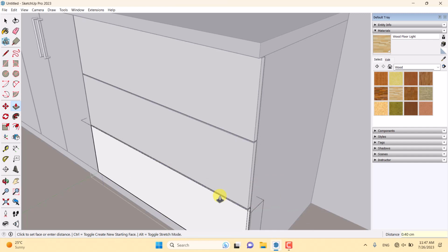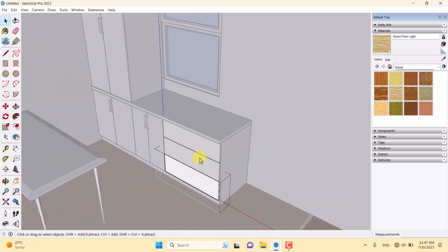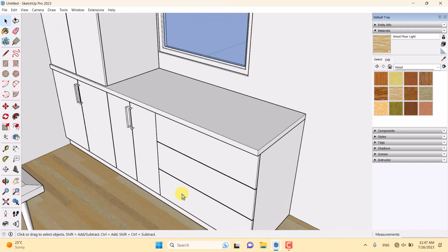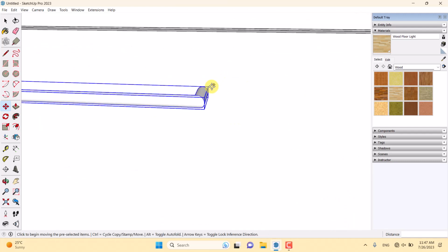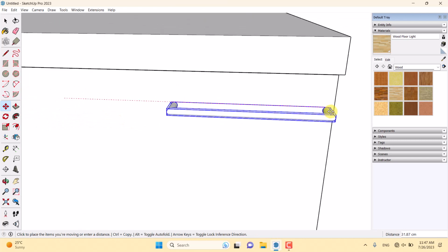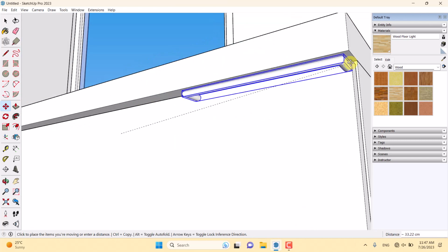So it converted for us. Now I want to save it, so I'm going to press Ctrl and S and save it in, for example, desktop. I want to call it interior N01, and you can change your save type to the different versions of SketchUp. So I'm going to press the save option in here, and everything is done for us.